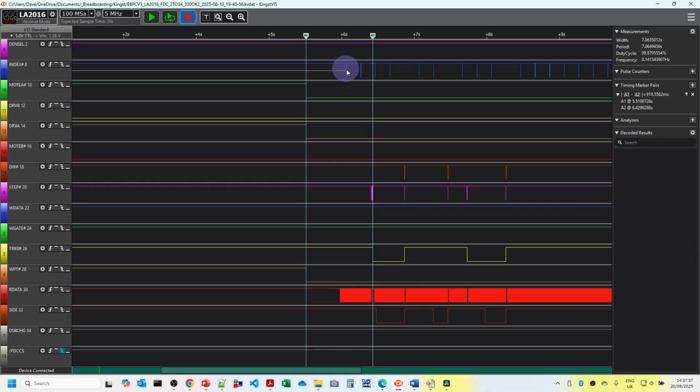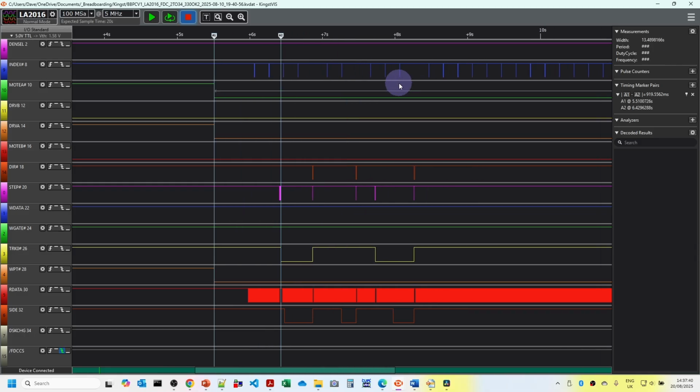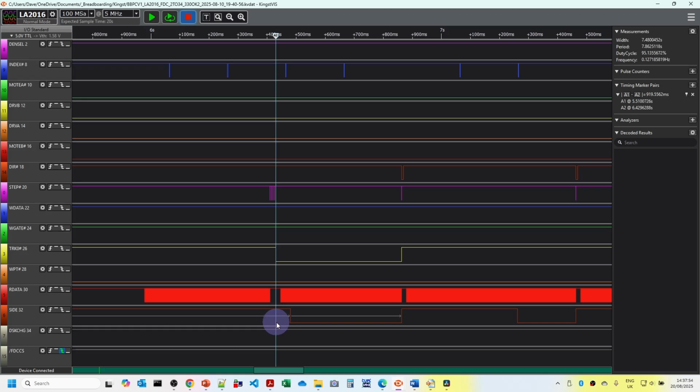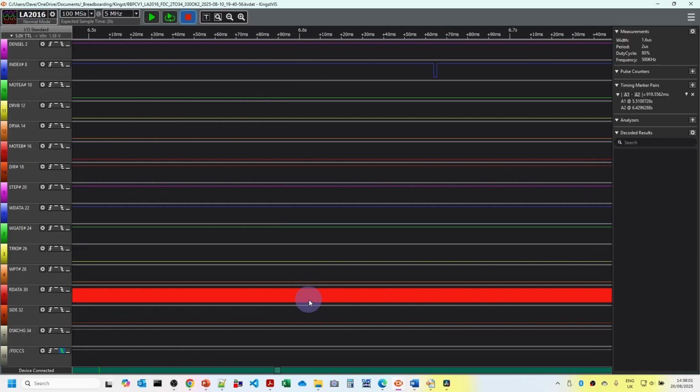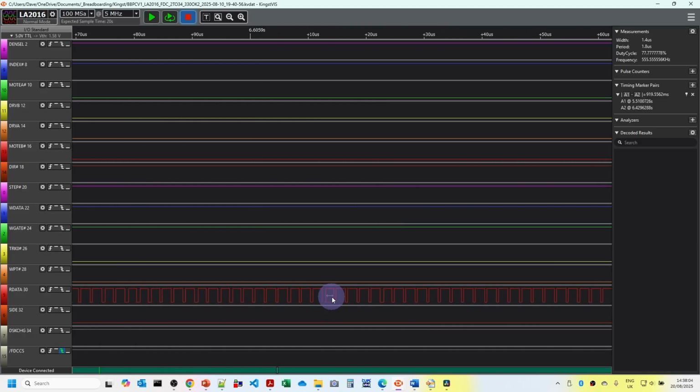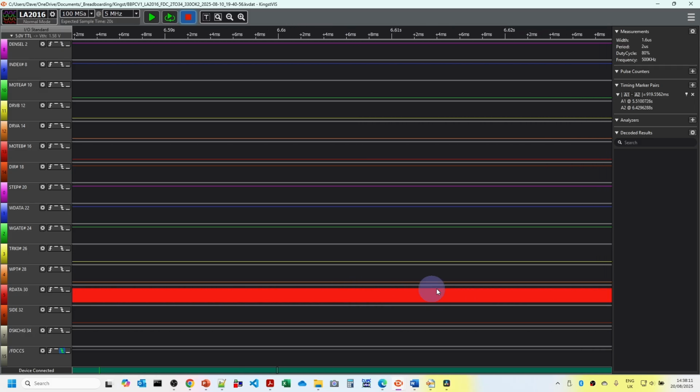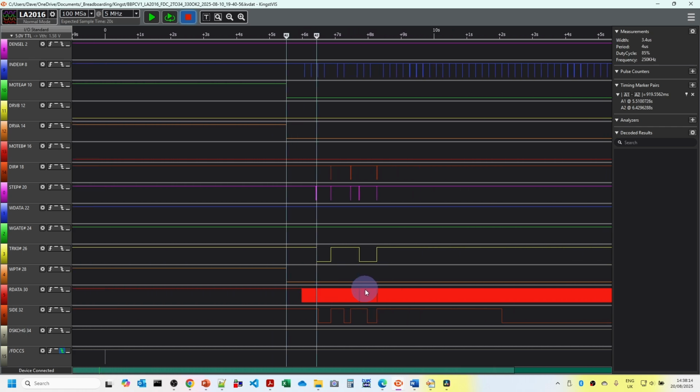We can see the various index markers here, which are typically going to be happening 5 times a second, since floppy disk drives rotate at about 300 RPM. And we can also see that as the operating system starts to boot, we're actually reading data off both sides of the double-sided floppy disk. The actual received data is MFM encoded, which is a variant of Manchester encoding, but understanding the encoding of that is beyond the scope of what we're going to be looking at here.